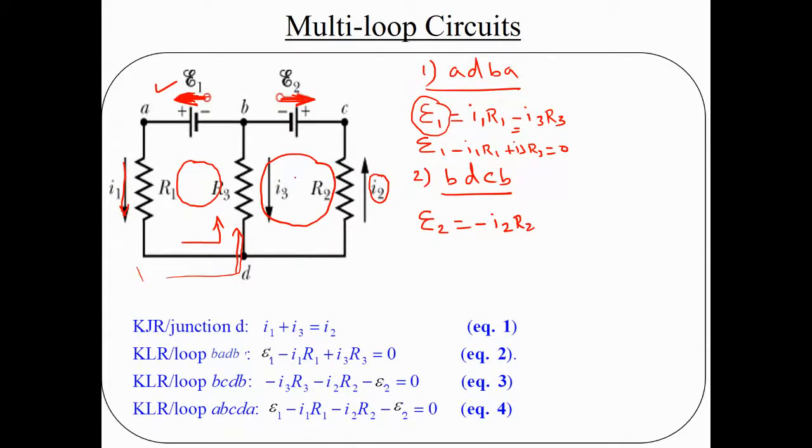Let's see this. My I3 direction and the red color direction are opposite. Am I right? How will the I3 current be in the same direction? No, different. Right. So what should be the sign? Minus I3 R3. Now, if you frame the equation equal to 0, I have to move this to this side. So what will happen, my dear? Minus I2 R2 minus I3 R3 minus EMF 2 is exactly equal to 0.